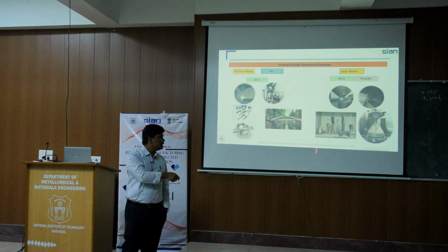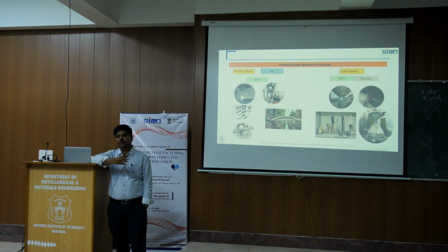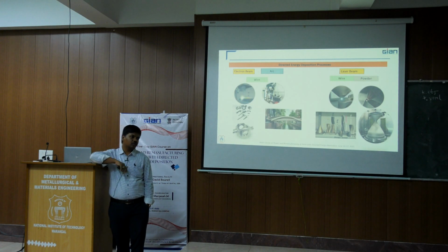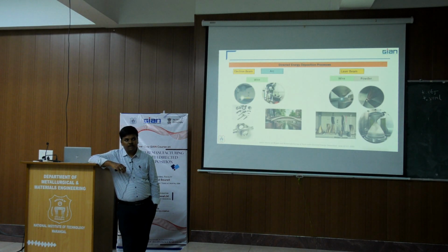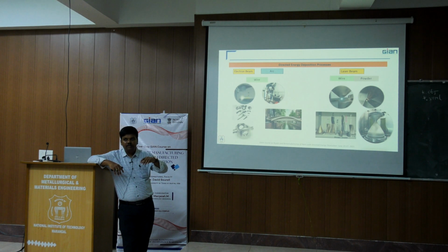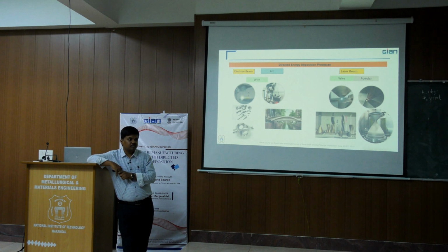But nowadays the metal has come up with a lot of advancements. Even the hybrid technologies, which will be talked about tomorrow. Means the machine has the capability to make the component as well as to machine it and develop additional features on the existing components. In the same machine, they have put CNC milling and drilling as well as wire-based depositions.